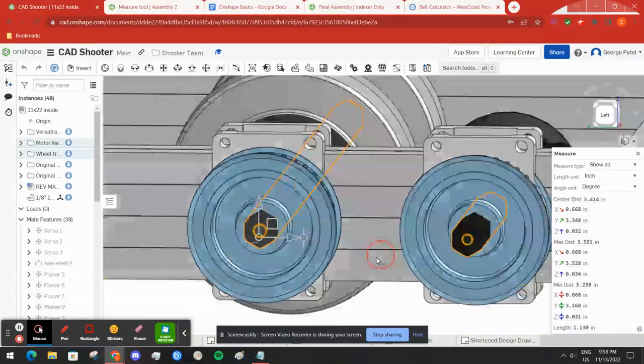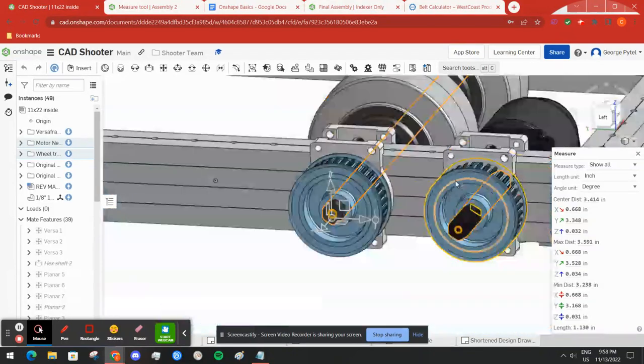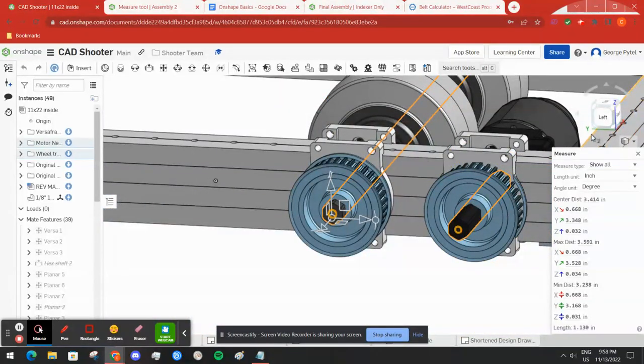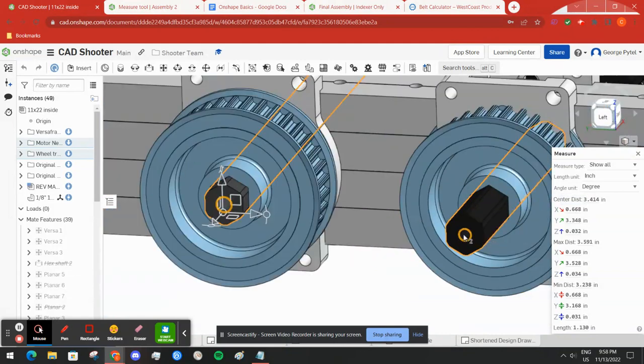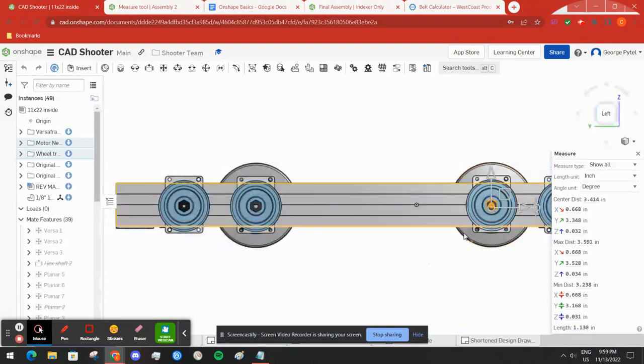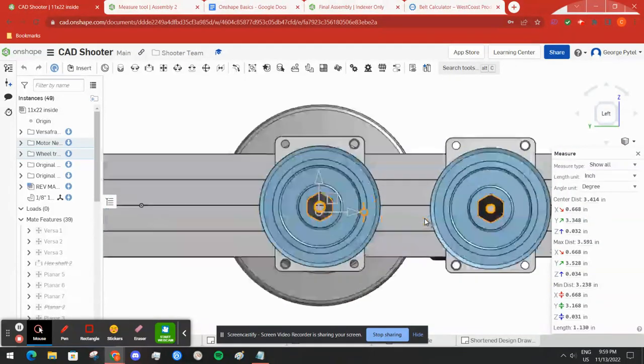So immediately, if I was to look at the dimensions on the orientations of the view cube, the x value, which is shown here, because it's the difference between this point and this point, does not matter. The z value also does not matter. So all we're looking for is this horizontal distance, which will be done in the y-plane. Knowing your orientations and your axes are extremely important for the measure tool because, again, it will give you many different readings that you will have to figure out and sort through.